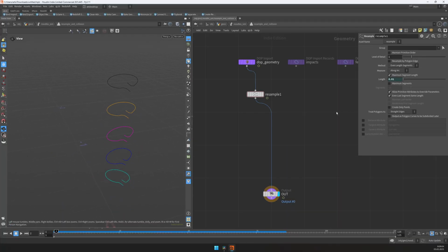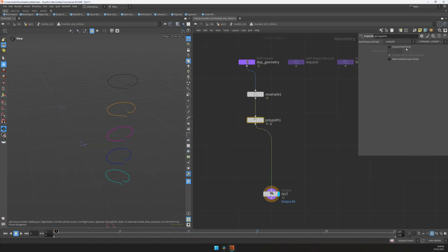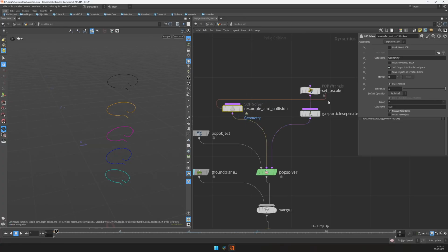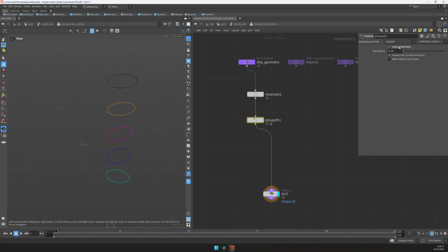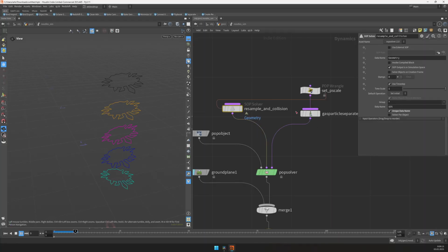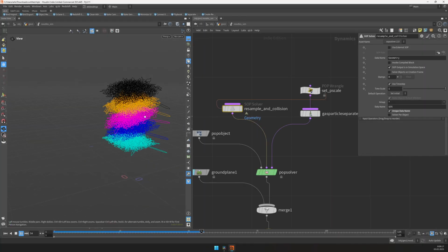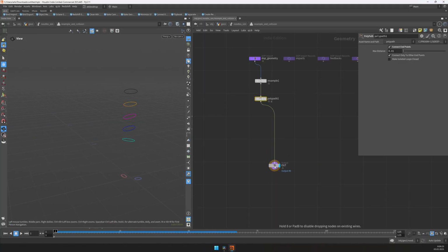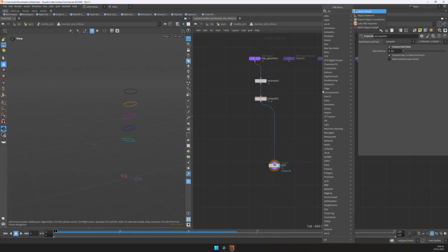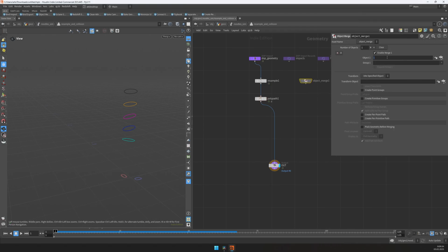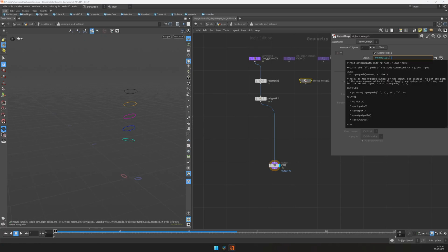We don't want that, so we're gonna use a PolyPath node, and I'll just rebuild the curve each frame. And you need to select connect endpoints. And right now, it's just fine. Also, we need to somehow solve the collisions with our mesh. For our collision mesh, we're gonna use an Object Merge, and again we're gonna use our old handy op input path expression.